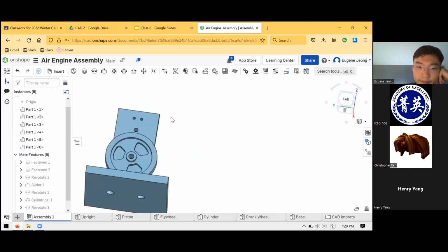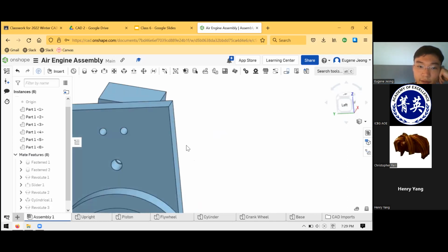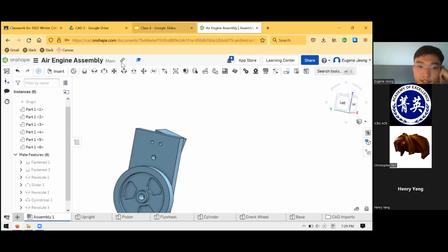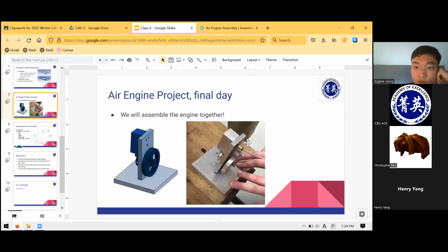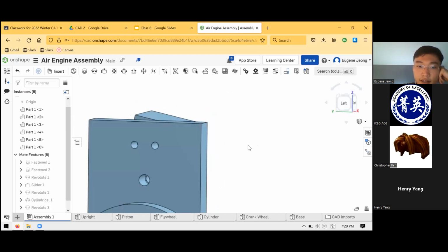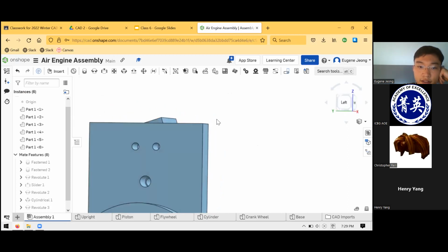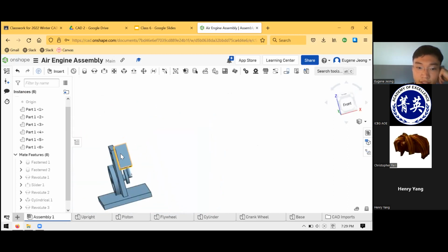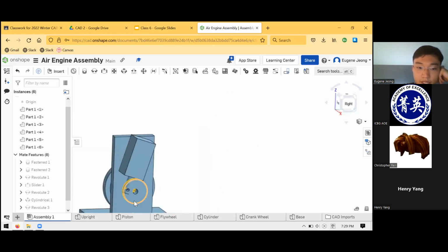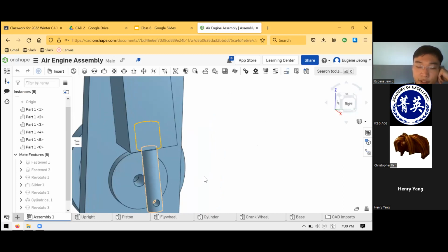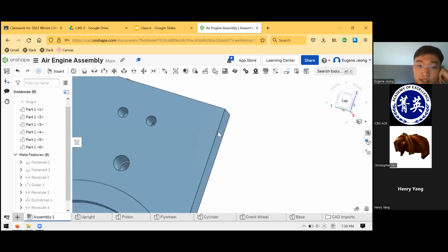And the way that works, you can see in the image, through one of the sides, that's your inlet for the air. So let's say it's this side. So when these two holes line up, the air is going into the cylinder. And as that happens, the pressure of the air is going to push this cylinder out further. And as that happens, it rotates, gets into this configuration, and then these two holes line up.